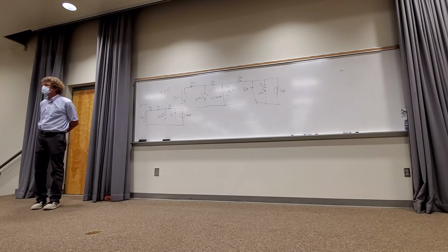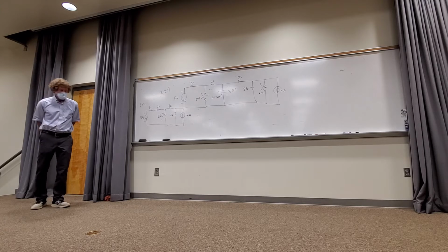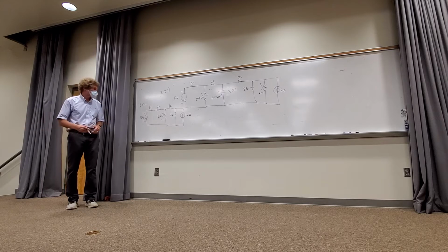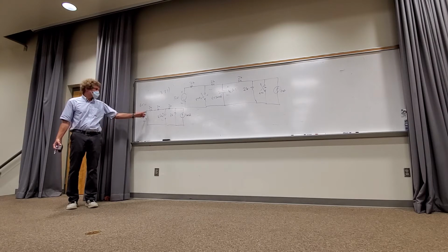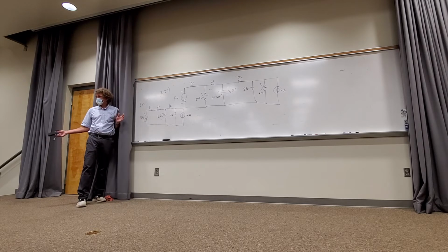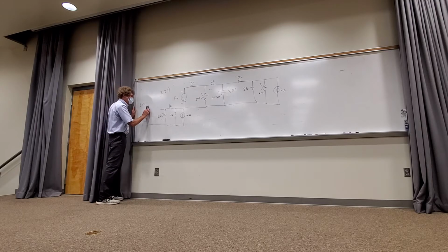And remember, you can use any tool in your toolbox to solve this. You don't have to use any one way. But they're ultimately after the voltage across that capacitor. I've taken the capacitor out. Y'all understand that? All right. Now to do this, here's how I would do it. You can do it any way you want. I combine things. You see you have 2K in series with 2K over there? Can you all see this 2K in series with 2K? Yes. Make it 4K, okay? Sure, just make it 4K ohms.